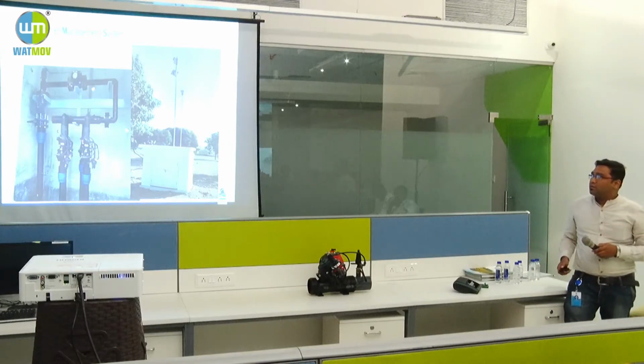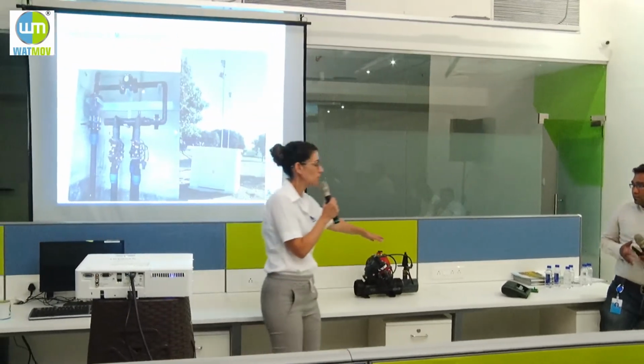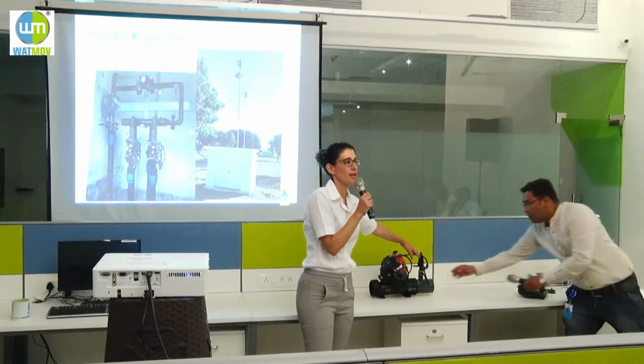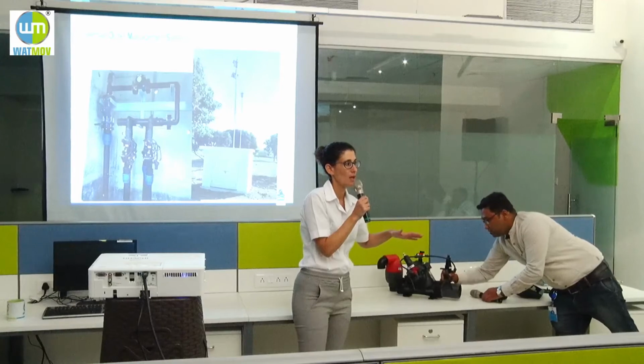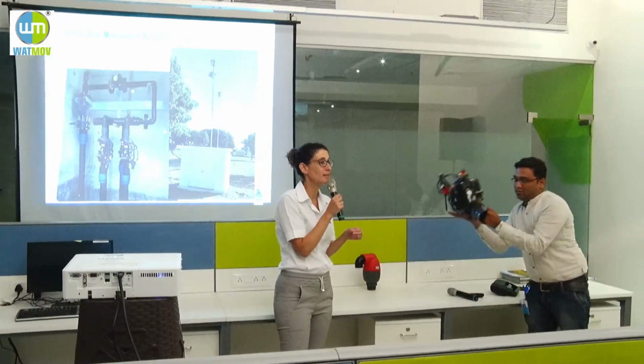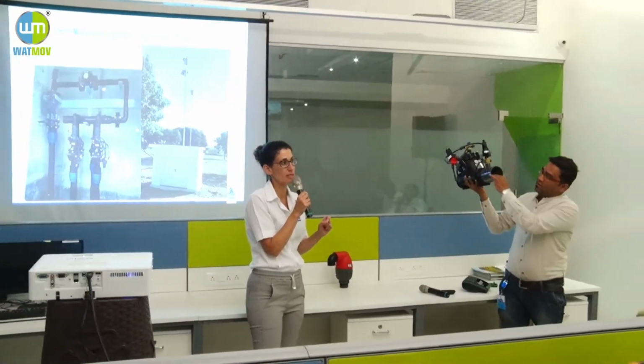Also, it's important, I don't think I put it in the presentation today, but this flow control method, the paddle, is unique to Bermad because it's not creating structural head loss like other flow control methods, for example the orifice and a differential pilot. When you put an orifice with a fixed machined hole per your design flow, you're creating structural head loss all the time, even when you don't need to limit the flow.